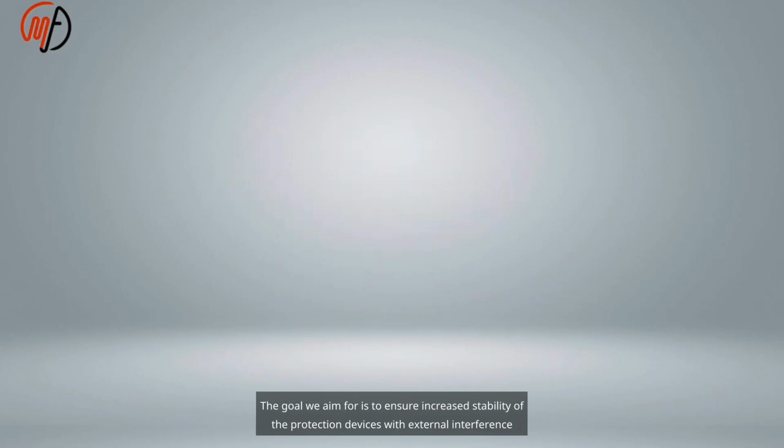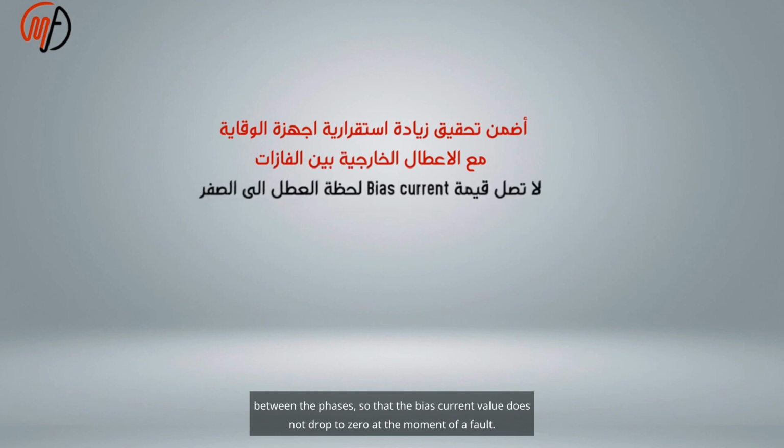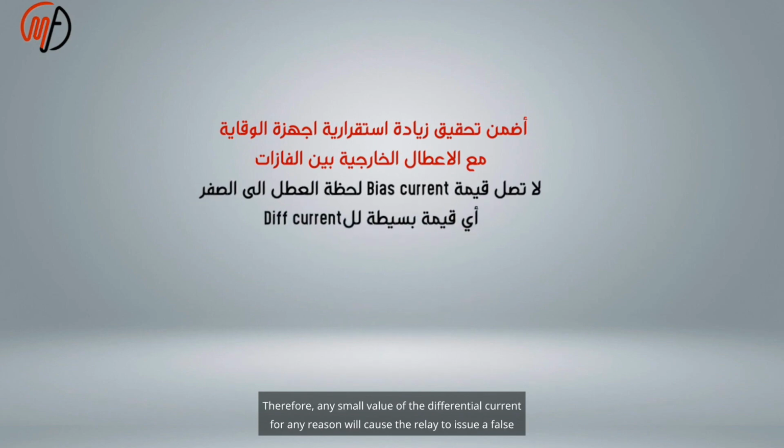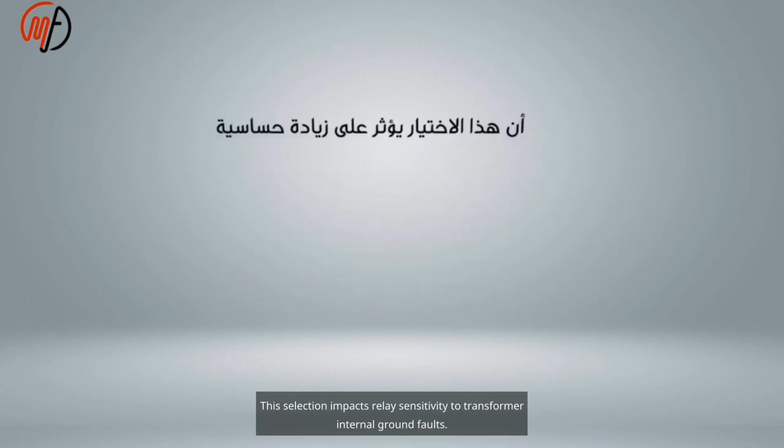The goal we aim for is to ensure increased stability of the protection devices with external interference between the phases, so that the bias current value does not drop to zero at the moment of a fault. Therefore, any small value of the differential current for any reason will cause the relay to issue a false tripping signal. Additionally, this selection impacts relay sensitivity to transformer internal ground faults.